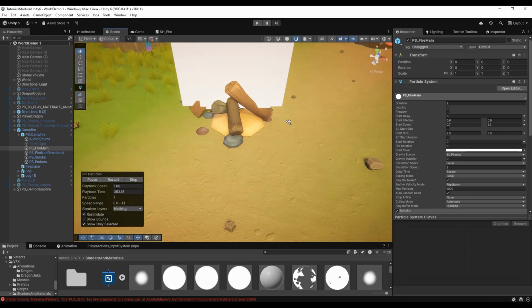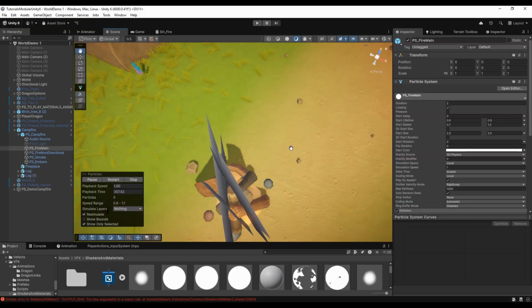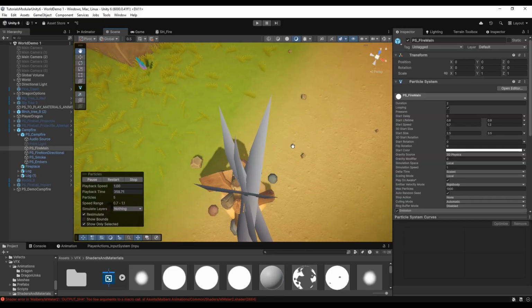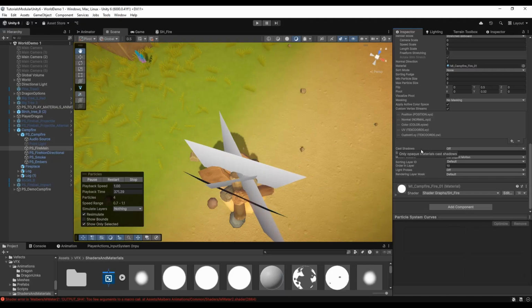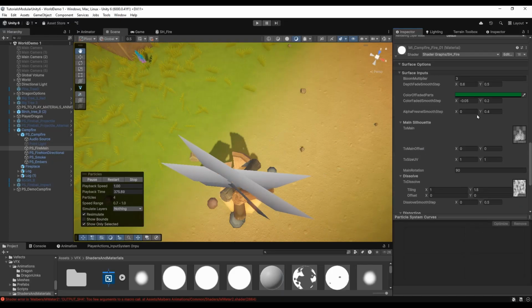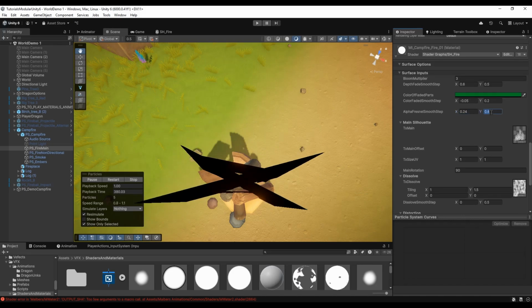So now it's all 100% white, and then we do a quick transition, but it's not becoming 100% black, so I'm going to play around with the smoothstep values to improve it. Remember, the first value controls the step, and the second value controls the smoothness.